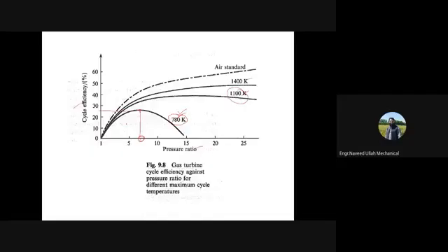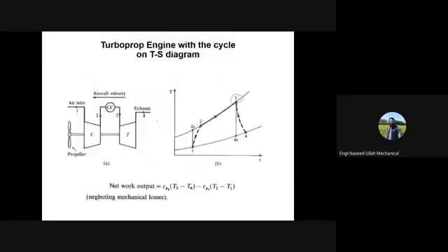It has also been observed that for the work ratio, for example at this 780 Kelvin maximum temperature, not all pressure ratios, but a pressure ratio of, let's say, 4 or 3 will give you the maximum work ratio. As you can see here, by pressure ratio we mean P2 by P1, the overall pressure ratio, remember?